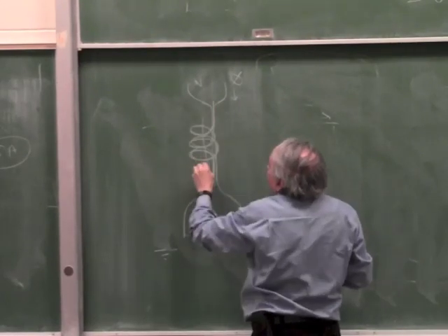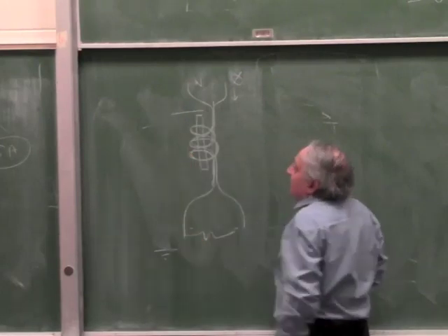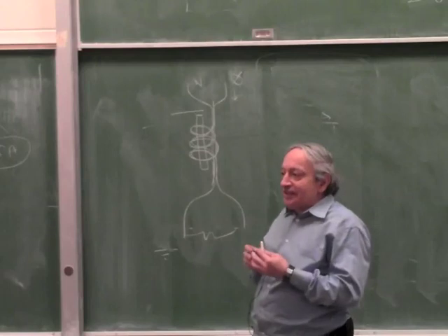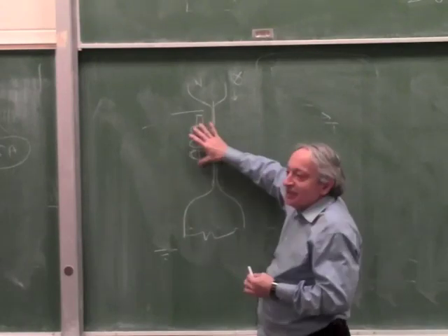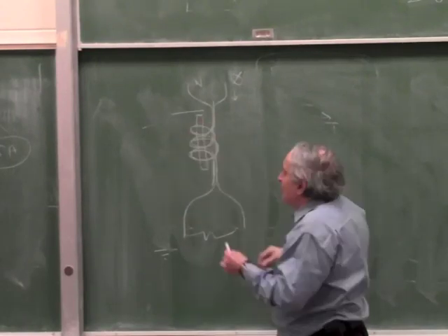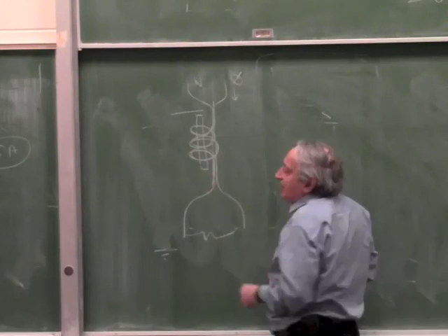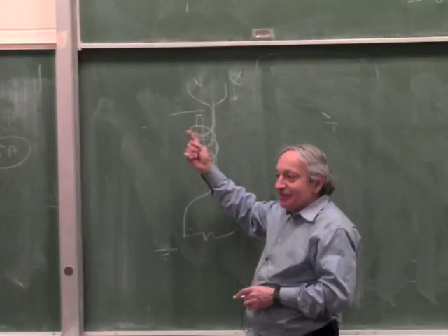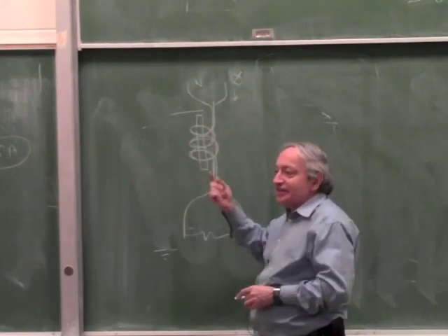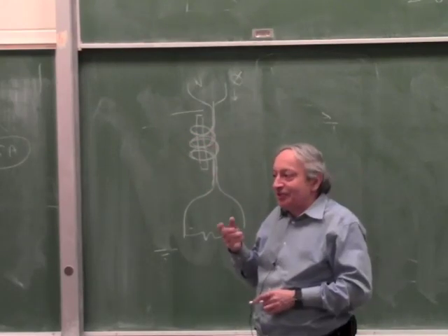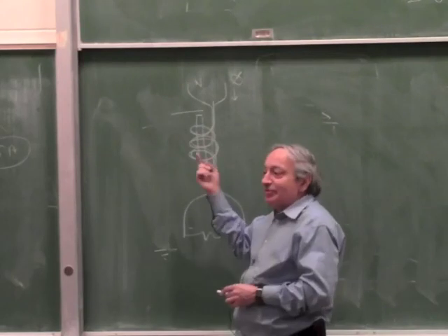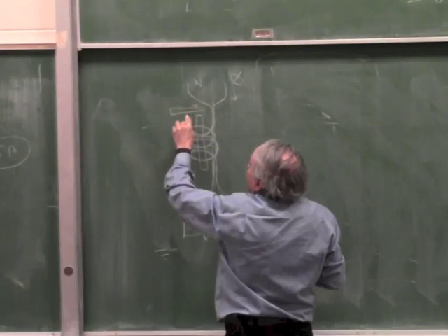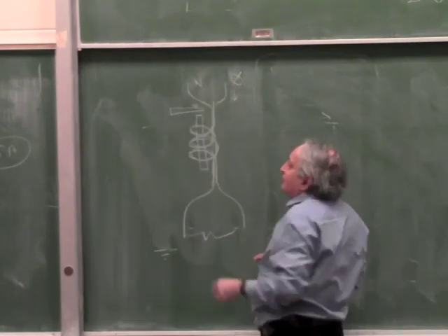And now you put an iron core, like a relay. Now, the two currents exactly cancel out normally, so this piece of steel is not magnetized. Now, the moment there is a small difference, say 5 milliamps, it will be the same as running 5 milliamps through the coil. But since the coil can have several turns, it amplifies the effect. Typically, it would have 10 turns, it's like 50 milliamp turns, and that is enough to pull an armature and trip a relay which disconnects the phase.